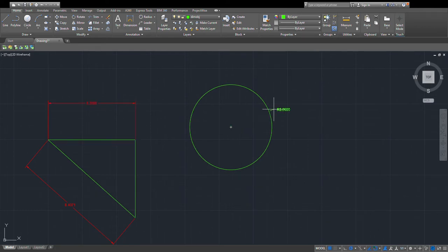So I just select, and now it has highlighted the center of the circle and given me a radius. I can also choose the location of where I want it to be. Alright, so it's giving me the R for radius. We set that up as a 3 when we drew it, so we know that is correct.